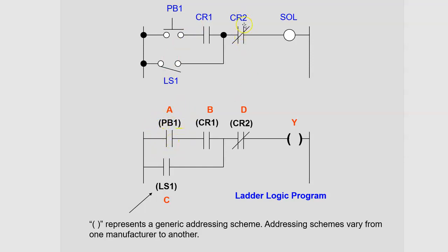And so notice here we basically translated this physical contact, normally closed contact, and we're representing that down here as examine if open. Now remember our discussion in the last video about logic continuity, so this might not necessarily translate this way. It depends. You have to understand the circuit, the logic of the circuit, to actually do that. But assuming that it does, then this is what you'd have as a ladder program.